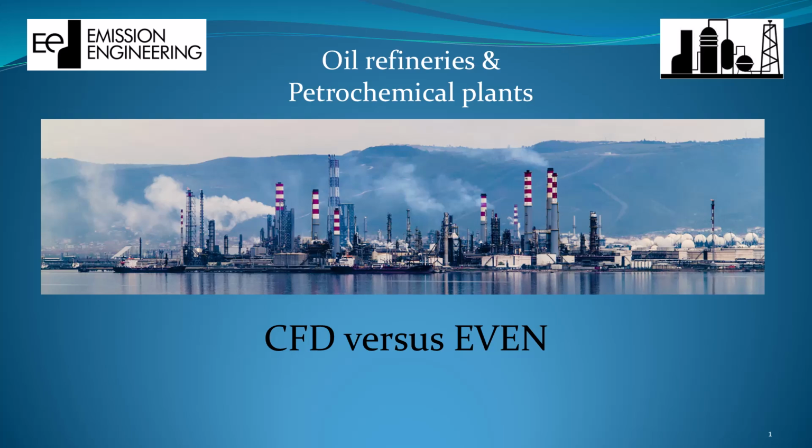Since the 2000s, computational fluid dynamics modeling, or CFD, became a tool to improve heater and air duct designs already during the detail engineering phase. For approximately 10 years, there has been an optimizing tool commercially available that measures air distribution in real time and allows for adjustment of air distribution on the running heater. Its name is Even, and stands for even or uniform air distribution respectively.